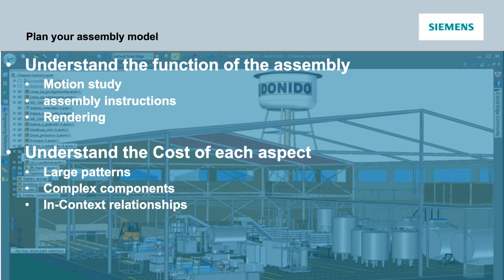Don't be afraid to make a separate assembly file for separate purposes. If you use the same assembly for everything, you may have to destroy one type of information to create another. Just make a copy of the assembly and the related sub-assemblies and use the same parts and go on with your work.